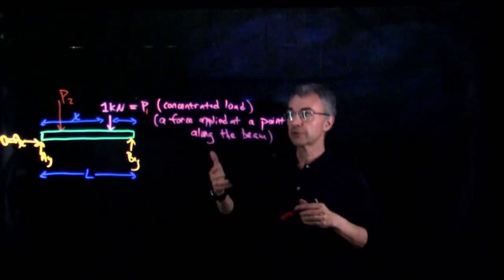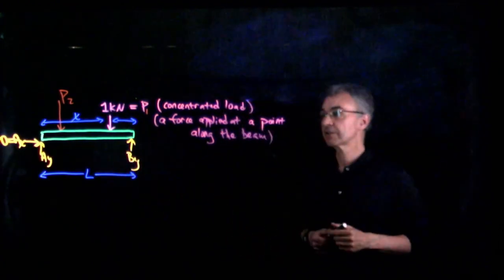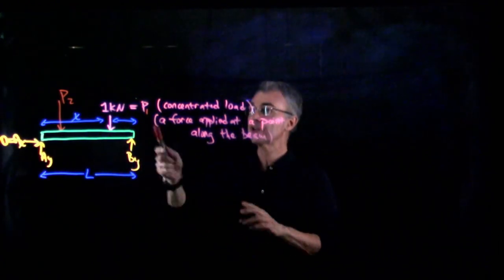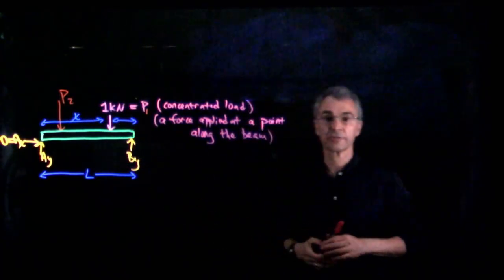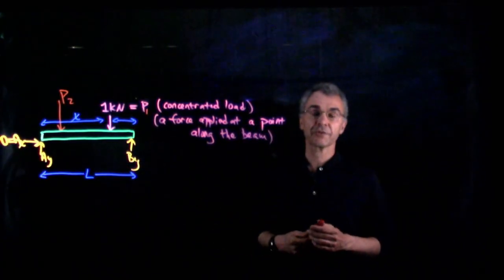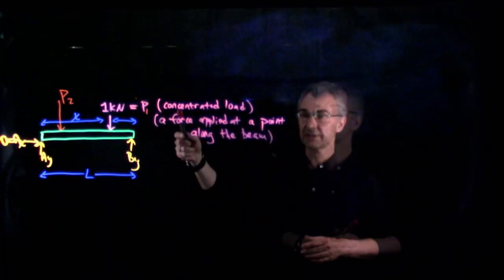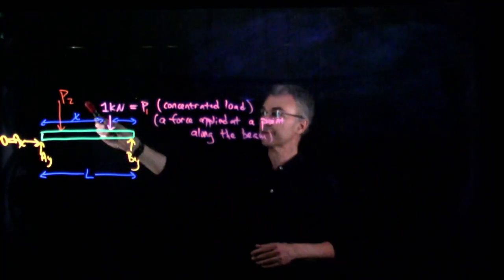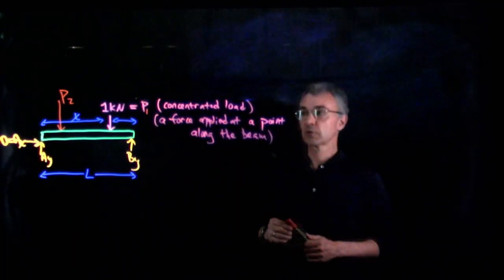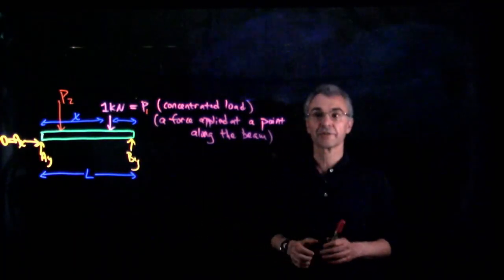And you would know how to solve for AX, AY, and BY using the familiar rules of statics as long as you know the values of these applied forces and you know where they act along the beam, you know the line of action of each applied force. All of the forces that we've considered in statics problems so far act at a point. In that sense, they're similar to these concentrated loads. A concentrated load like this would be analogous to putting maybe a safe or a very heavy dumbbell at one point along your living room floor.